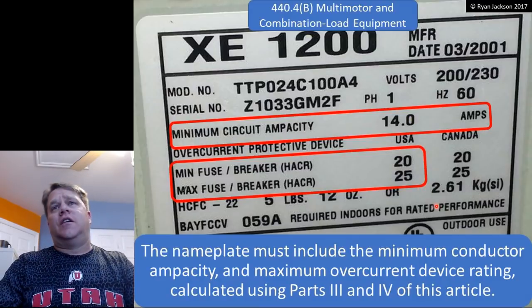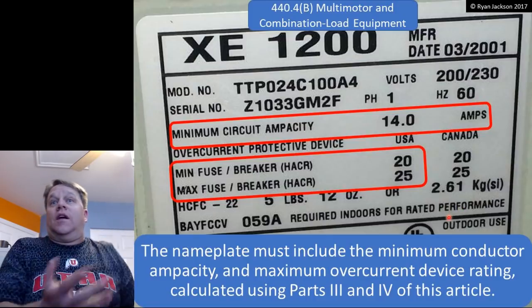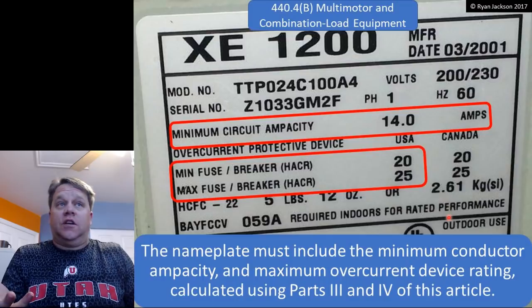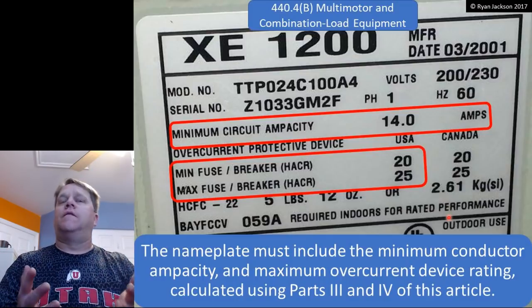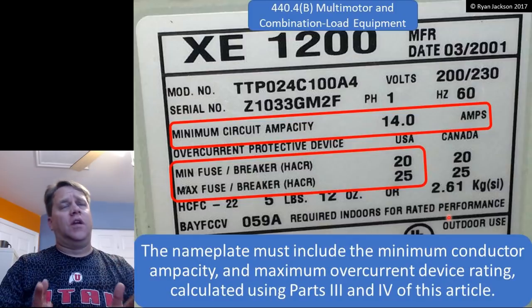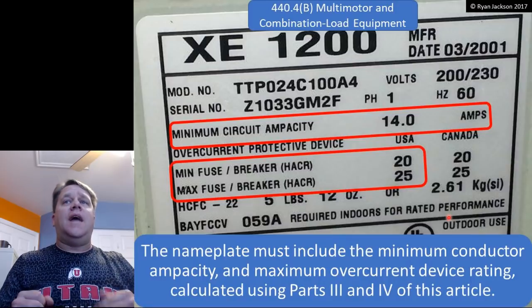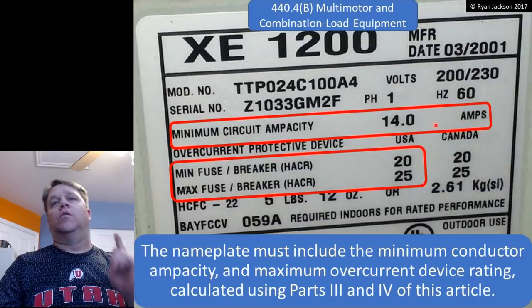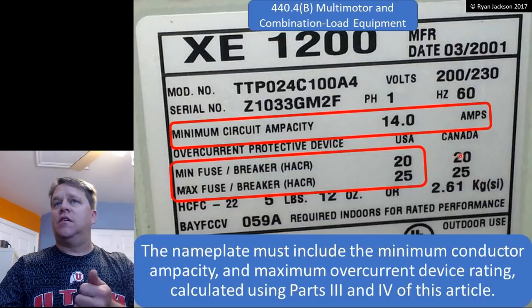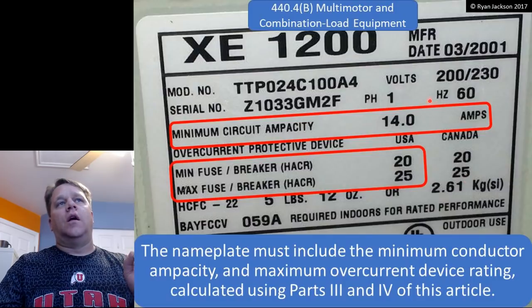It's the same thing with an air conditioner motor. You reach into the motor or you pull the tree out or whatever it was that's creating the overload condition, right? And then you turn it back on and everything works fine. You have ground fault and short circuit protection. You know the 25 amp breaker is going to trip if I take those two 14 gauge wires together. And if the motor starts pulling more current than the ampacity of the conductor, it will shut itself off. It's thermally protected. It's inherently protected. So that's why I can use 14 gauge wire on a 25 amp breaker for this particular unit.